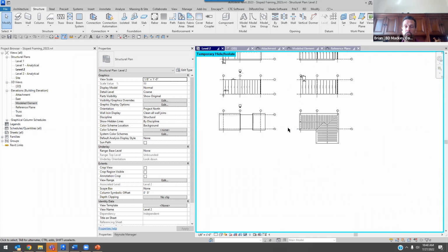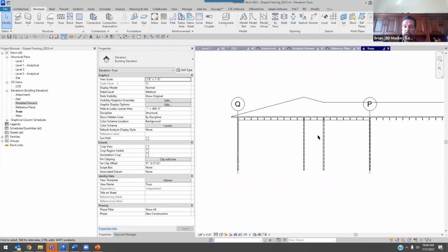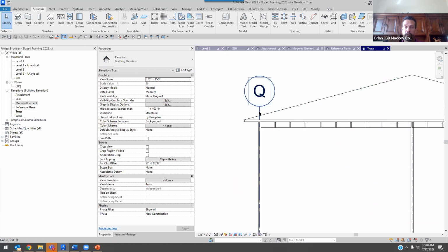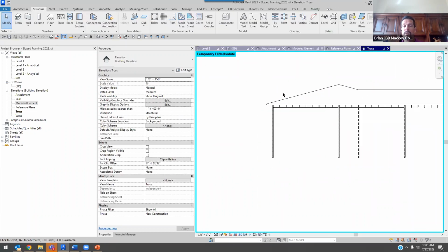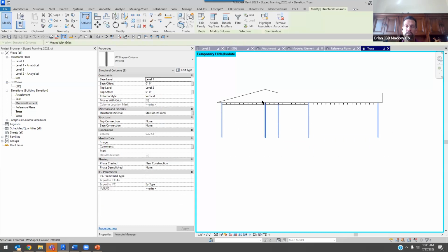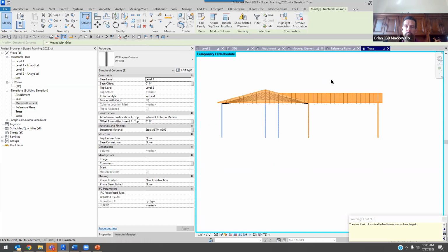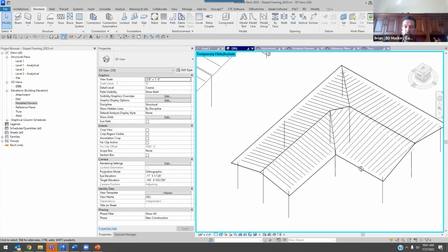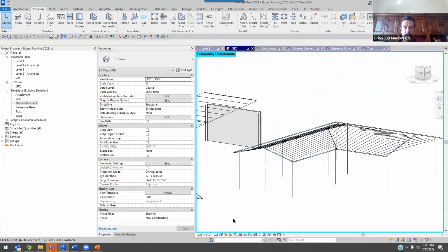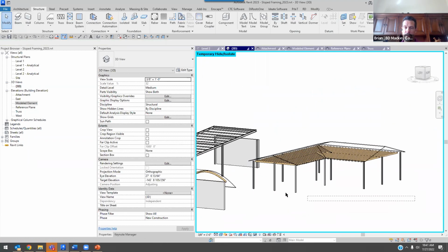Then if I go into this elevation, now if I come over here, I'm going to hide my grid lines. I really should have made those taller. Go hide my grid lines with the sunglasses. But now all I have to do is grab all of these columns, hit the attach button, attach them to, I'm going to go to the intersection in this case, attach them to here, and boom, all of those went along for the ride. I now should probably do that here. I'm going to go to my medium level of detail. I'm going to grab all these columns here.